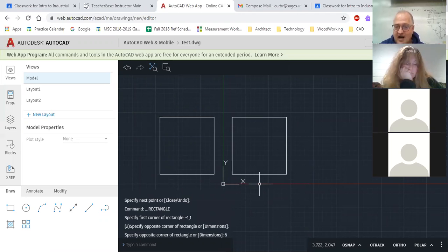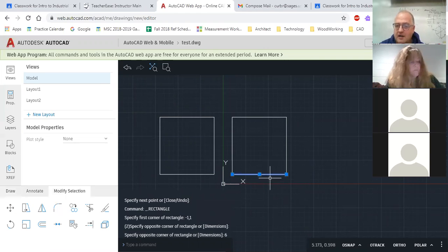It's the same size, two different ways to actually draw this. Now, there is a difference though. Notice before, remember I said about entities and the way AutoCAD looks at this. A square using the line tool is made up of 4 entities. Each one of those lines, there are 4 entities. Using the rectangle tool, it is 1 entity.